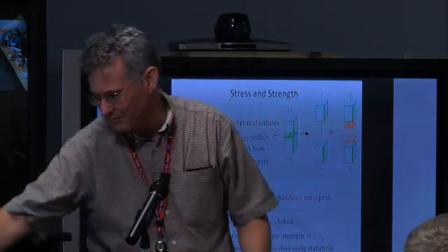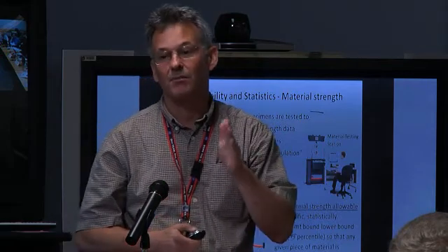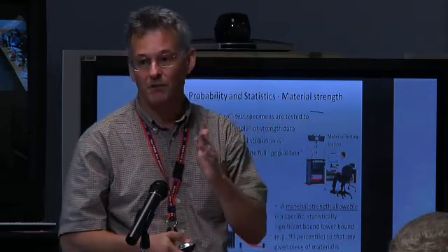I took this one sample and broke it, and if I had some instrumentation on it, I could tell you what load it broke at. But if I did that again, I would get a different answer. It'd be close, but it won't be the same thing. So probability and statistics, here's one use of it, material strength. We actually will test many identical samples. So I got the first one I broke. The second one, you break that and you take your measurements. A third, take that, break that. And what you get is at each place it broke, you have a different strength, a different load at which it broke.